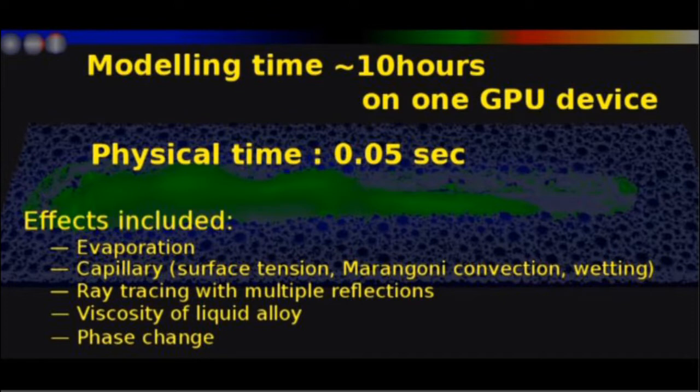For us to be able to see the details of what's going on, we have to measure somewhere on the order of 10 to 20 kilohertz. So that sets up what is a challenging ability to read those in and process those and do analytics on those types of signals to be able to see all of those details that are actually happening.